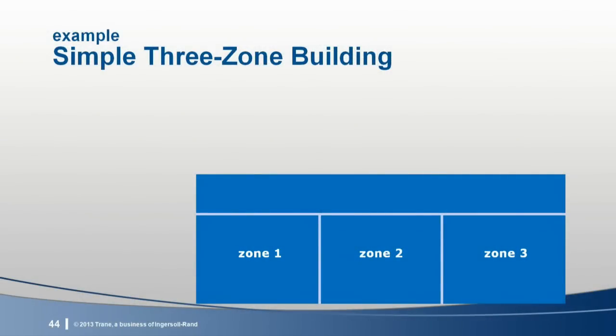To demonstrate the procedures for calculating system level intake flow, we'll use this very simple 3-zone example. As I mentioned, for each of the 3 configurations, the system calculations build off of the exact same zone calculations. So for our example, the zone outdoor airflows have already been calculated to be 300 CFM for zone 1, 400 CFM for zone 2, and 500 CFM for zone 3. We'll demonstrate the system calculations assuming operation in cooling mode. So zone air distribution effectiveness is equal to 1 in each zone. But I will mention how the results might change in the heating mode later on.